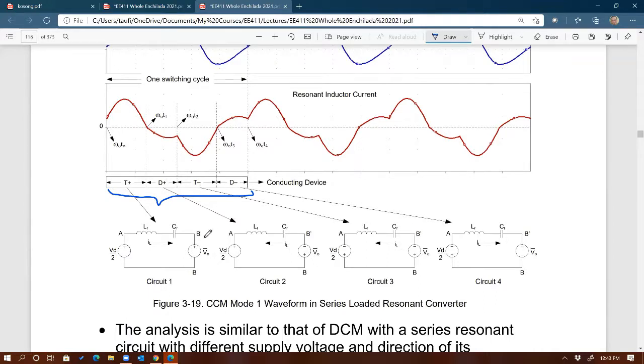And look at the circuit. Every single state related to which device is conducting gives you resonance. See? Resonant, resonant, resonant again. That's why you always have sine wave after sine wave, with different peaks, just like before. So the same kind of analysis. I'm not going to go through this in detail. One important thing for you to notice is which device is conducting at any given time.